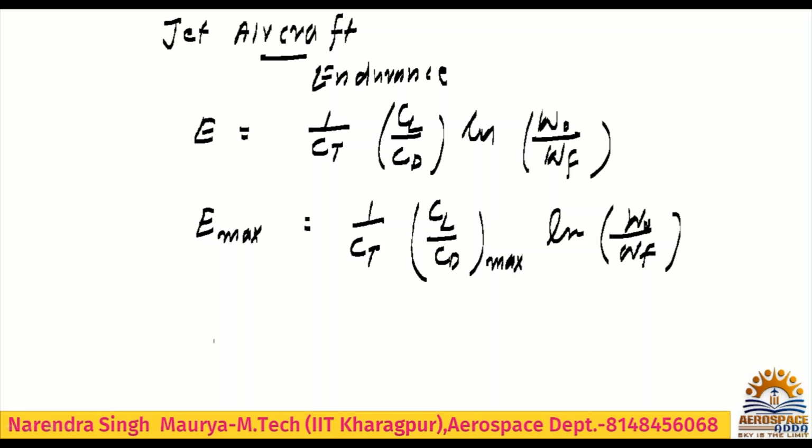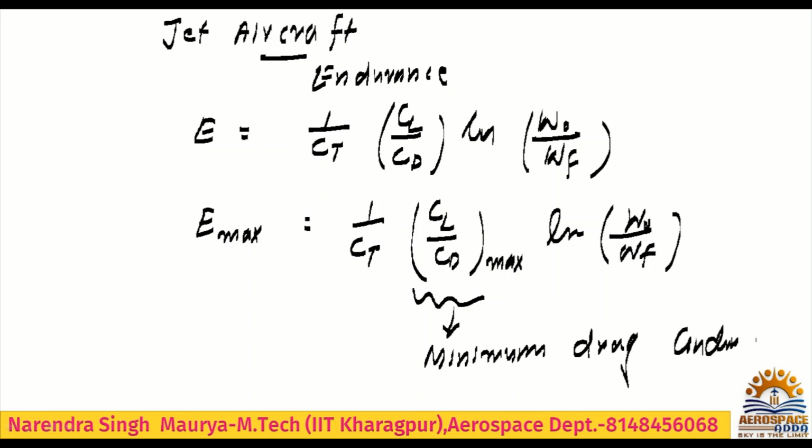So what is this term CL by CD? This CL by CD max is also known as the minimum drag condition. If you want to calculate maximum endurance, then you have to apply the minimum drag condition. That is the conclusion we got here.